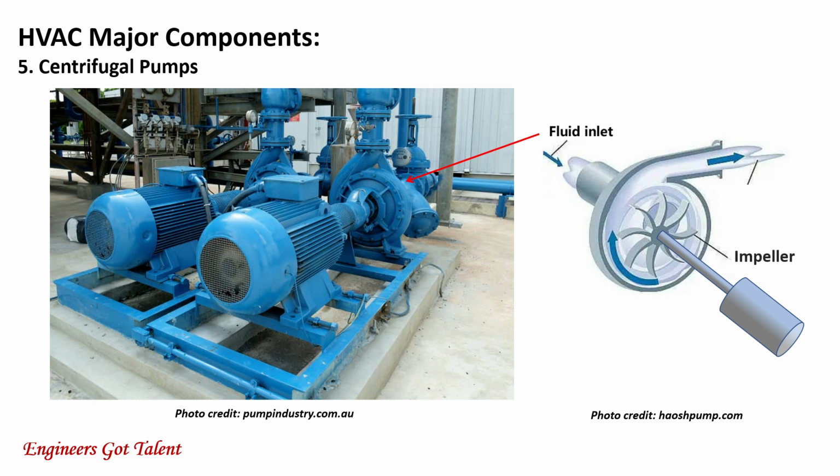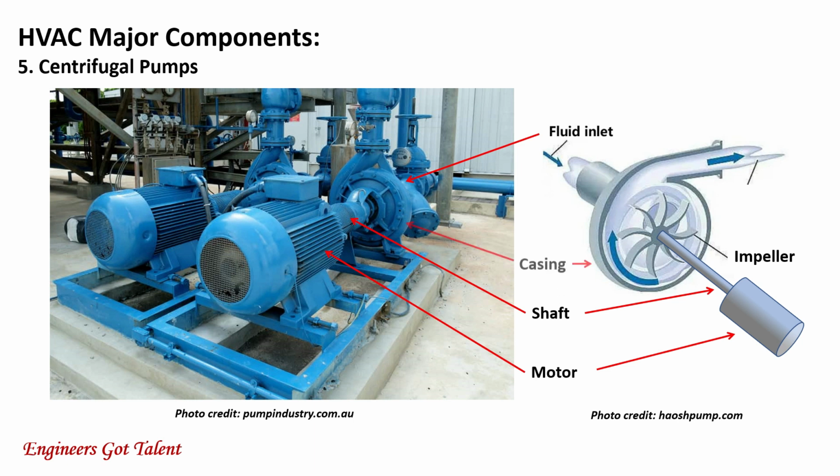The impeller rotates and draws the incoming water. An impeller is a rotating steel disc with vanes. It is powered by an electric motor. The impeller transfers energy from the motor to the water by increasing the water velocity radially outwards from the center of rotation. When the motor turns, a centrifugal force is created, causing the water to be drawn towards the impeller. The water is directed around the circular casing. The water is then discharged at the volute.